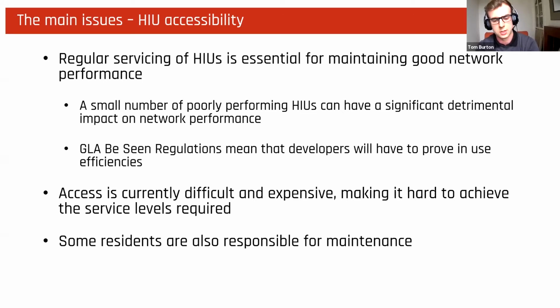And what we also see sometimes is that some residents are also responsible for maintaining their HIUs, which means you've got third parties maintaining the system who don't know anything about how the system has been designed to operate. They don't know the set points of the network, the hot water, space heating, and sometimes also the training levels aren't as good as what you would get from a qualified HIU servicing engineer.